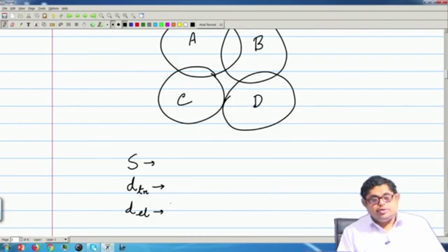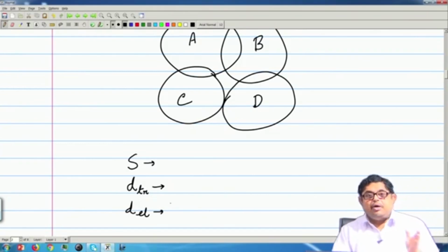So, what we need to do, you see that this involves the change in the amplitude, that we will see is due to the complex ratio, because all these are RF signals. RF signals can be represented as a band pass signal, an RF band pass signal. So, they can be represented by a complex envelope. I think in communication you have learned this concept, complex envelope. Then they become low pass signals, complex envelopes are low pass. So, it is a complex ratio. So, there is a phase of the ratio also, we cannot throw it. So, at RF level or at IF level, without changing the phase, we will have to take this ratio.